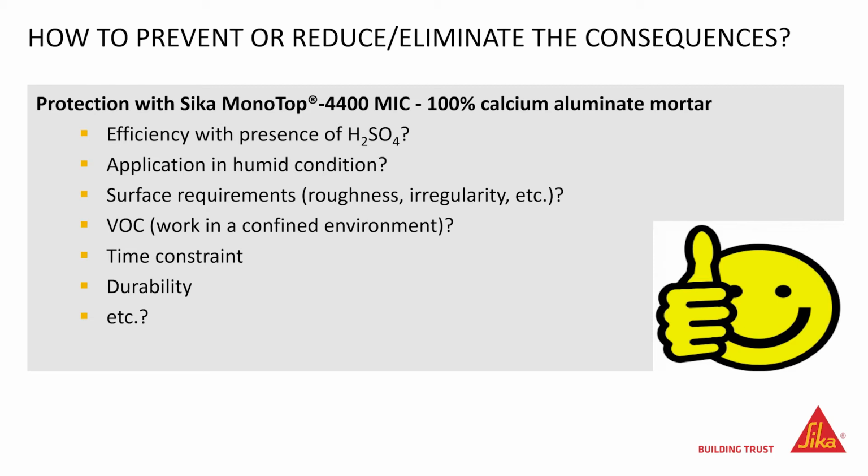Surface requirement. Mortar needs to be applied on rough surface and does not require a specific smooth finish. VOC. This is a water-based system. Time constraint. Typically 12 hours after application, handover can be done. Durability. Proven by test experiments as well as from investigation on old projects up to 23 years old.